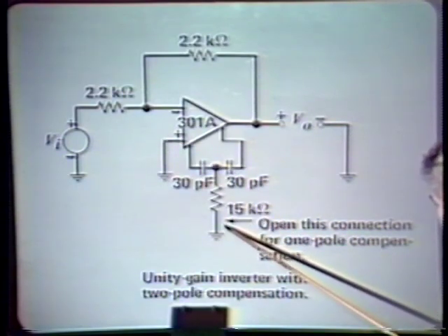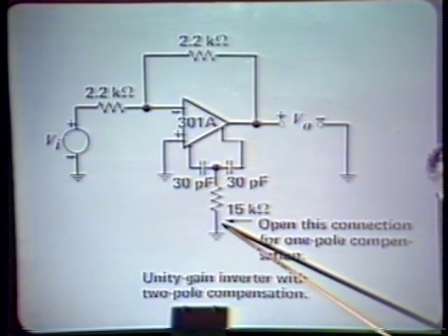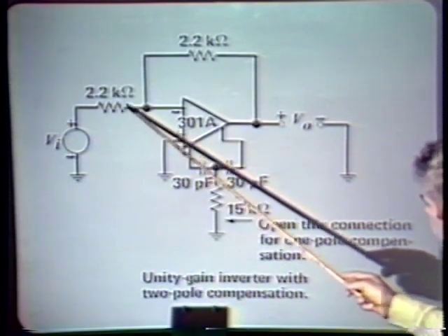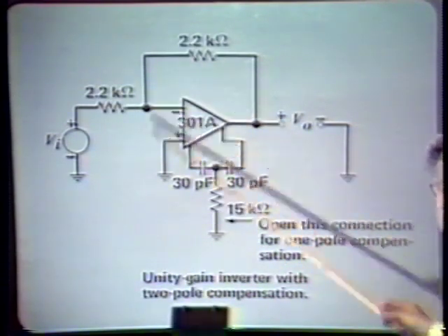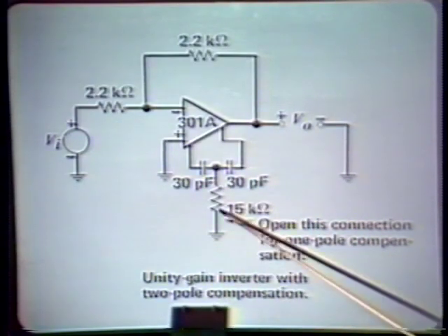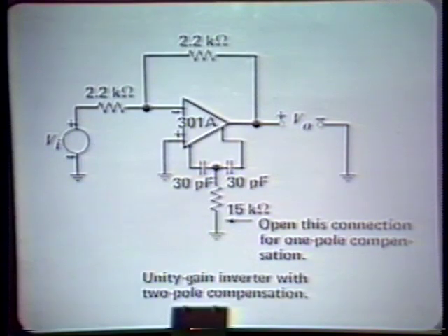The 0 comes in at about 100 kilohertz. So this combination of values, as I say, gives us the 1 over s squared roll-off, which breaks back to 1 over s in the vicinity of crossover.